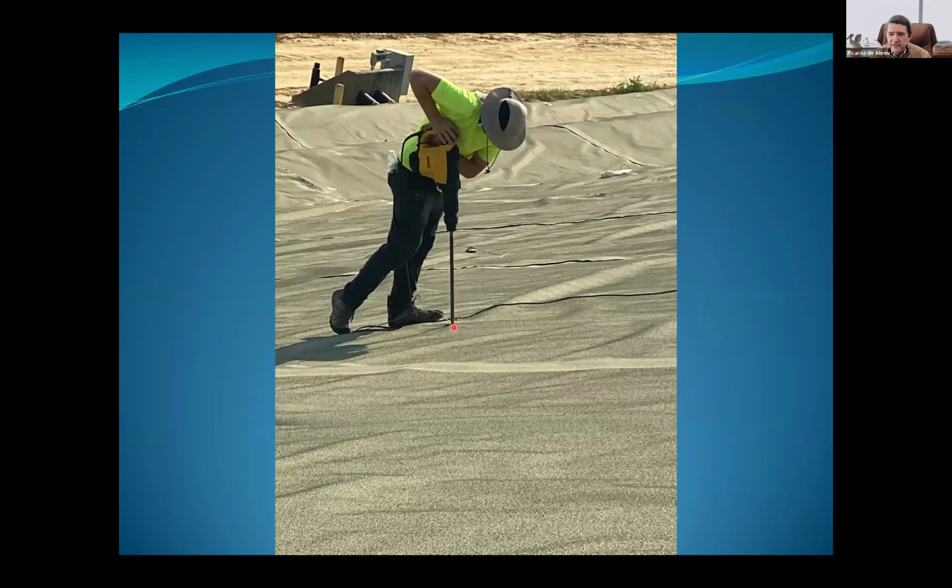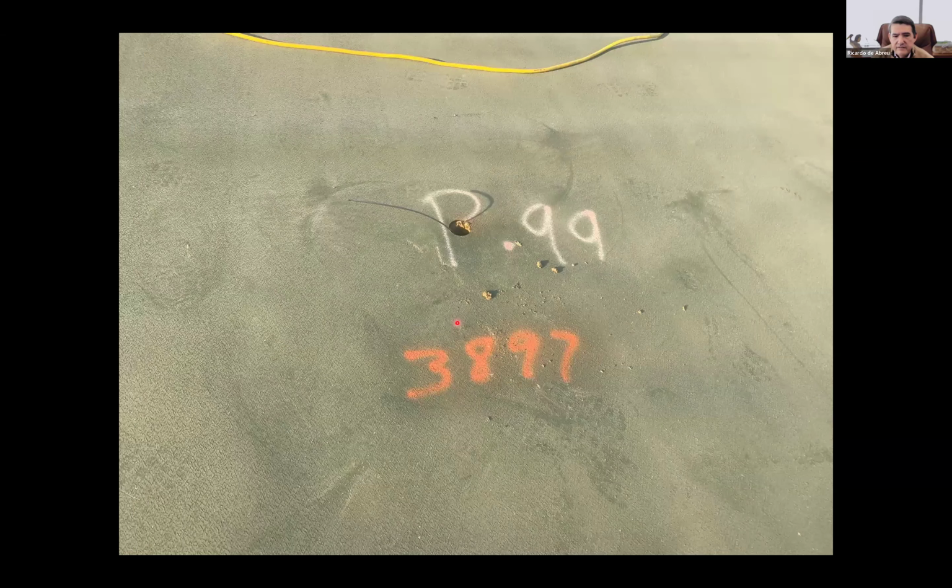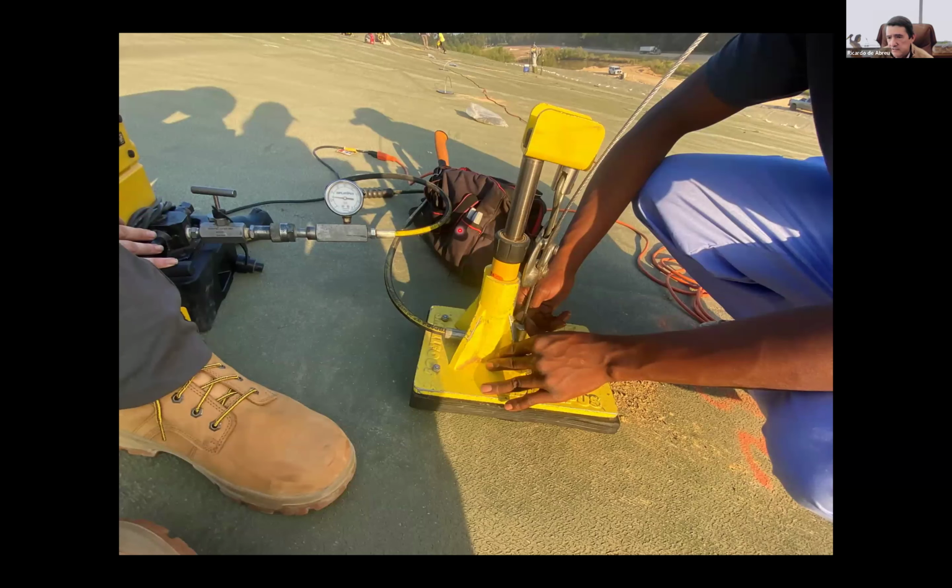So what you do, you punch in basically using an electrical demolition hammer. You puncture, you push the anchor inside, and this takes some time. But I mean, we could install close to 150 anchors per day this way. So you installed that. Here's a picture of an anchor that has been installed, with the tendon sticking out of the hole.